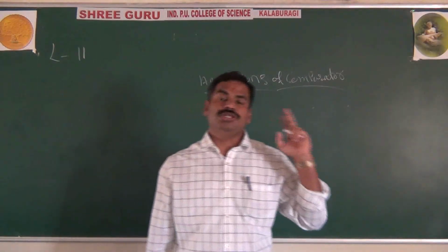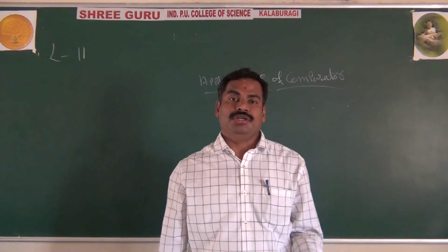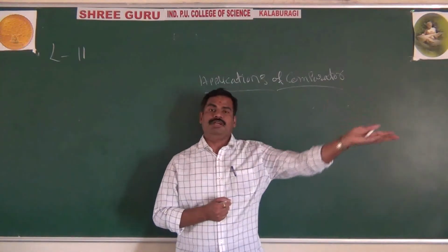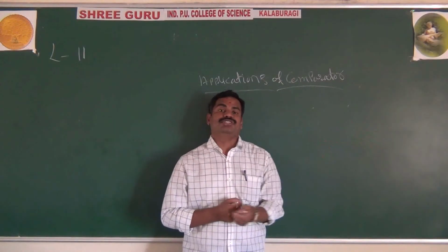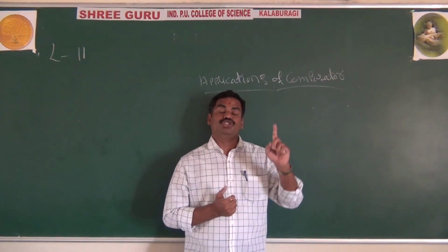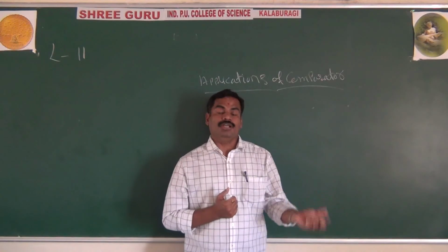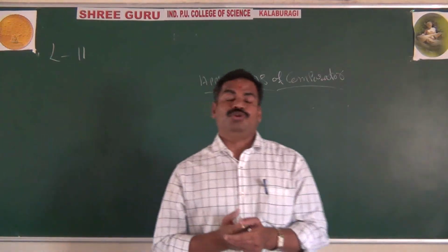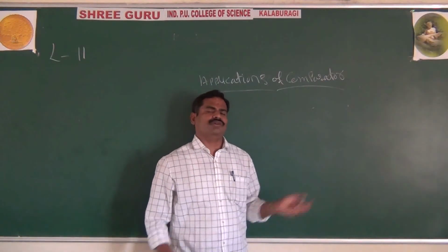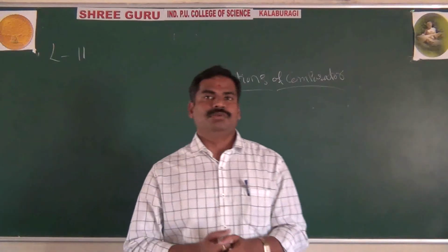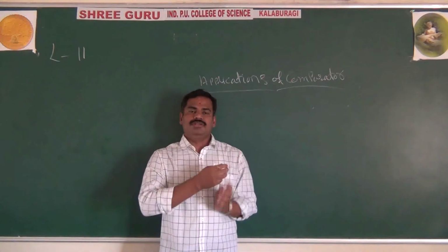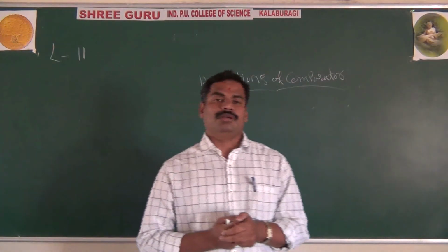It means in your zero crossing detector, if the input voltage increases above 0, if the input voltage is more than 0, we may get the output. It means sometimes we may get noise at the output. But here in the Schmitt trigger, the input voltage should always be more than or equal to the positive saturation or negative saturation, then only you get the output. It means you can reduce the noise in your Schmitt trigger. This is in brief about the Schmitt trigger and zero crossing detector. These are the two important applications of your comparator.